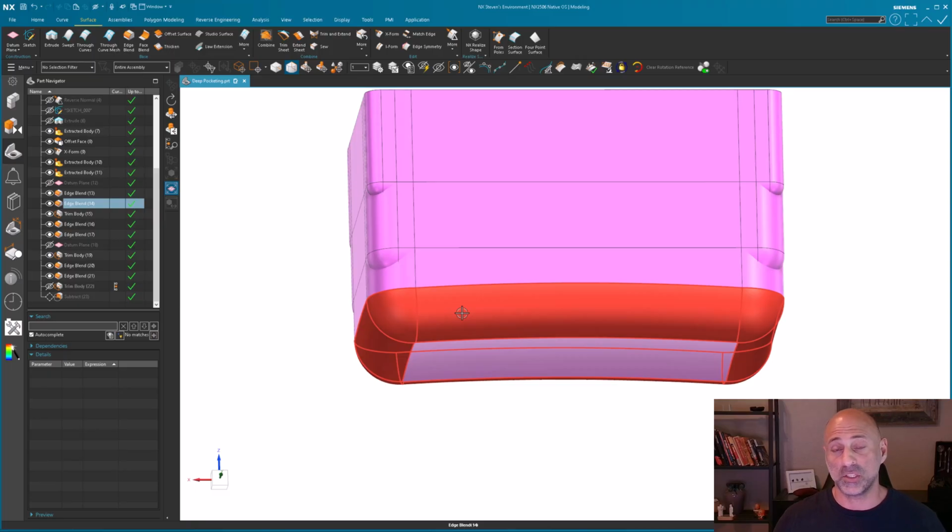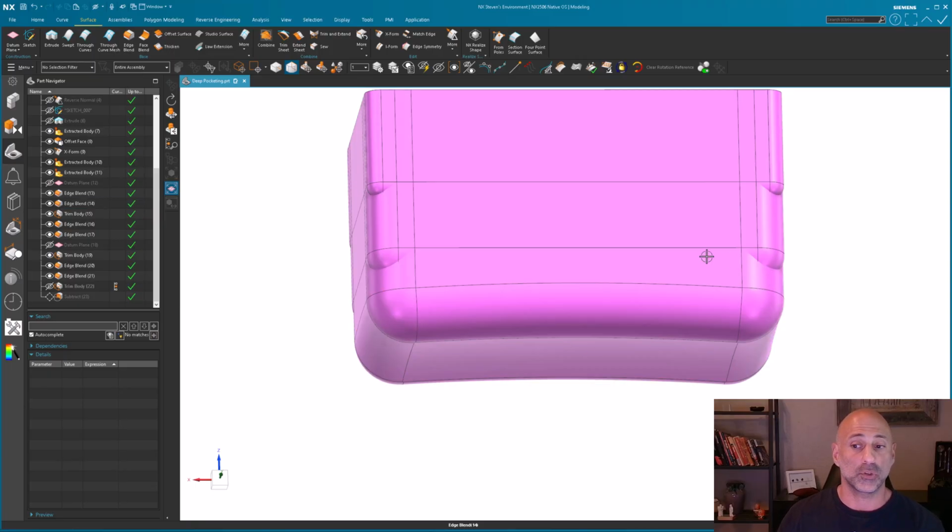Maybe there are some stress issues where you have to have a minimum radius size, but if that's not the case, and you have an 8-inch deep pocket, you're going to have to figure out, can I use a 16 millimeter diameter? Can I use a 10 millimeter diameter? Can I use something, maybe 19, whatever that may be? So you want to figure out the smallest diameter you can use with a cutter that length that gets into the bottom of the pocket. And that's what this first cutting pass is for.